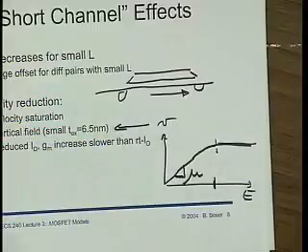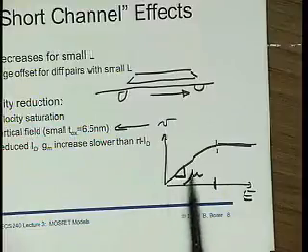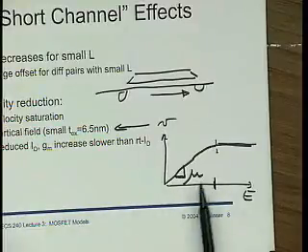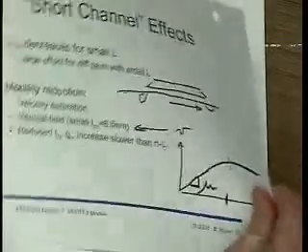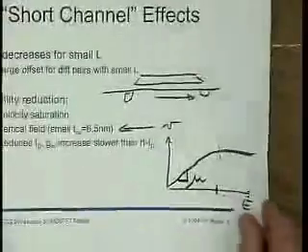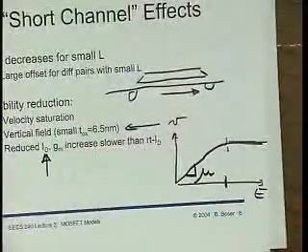So this whole concept of mobility, I guess, is a little bit of a crutch, because it's reasonable down here, there is really a proportional relationship between velocity and electrical field, but for a higher electrical field, that's just plain not true. And I guess I just got a break when I went to school that we safely always operated down here and it didn't matter. And well, you now are facing the whole thing, and so you got to worry about this part. All right. So the net effect, of course, is that we end up with less ID than we think that we should have.